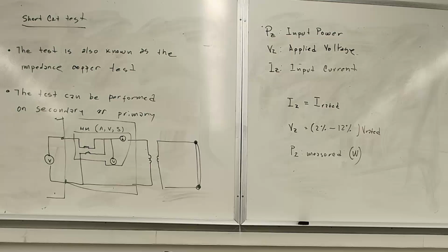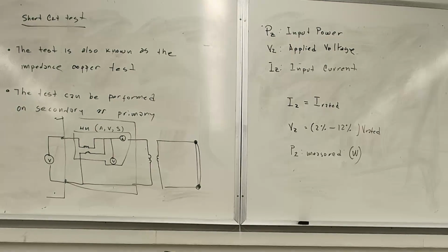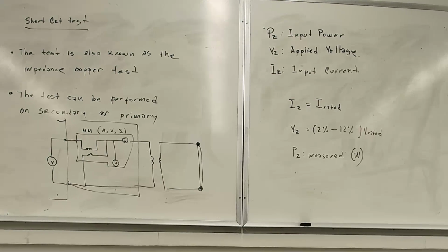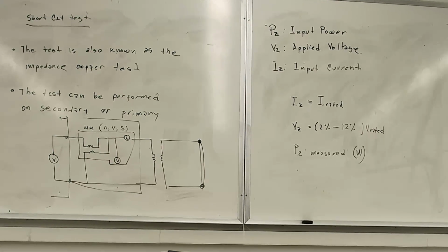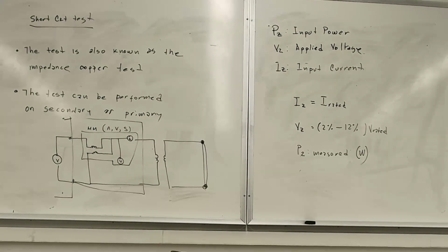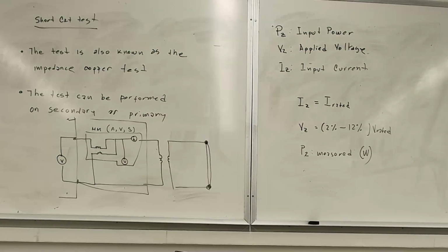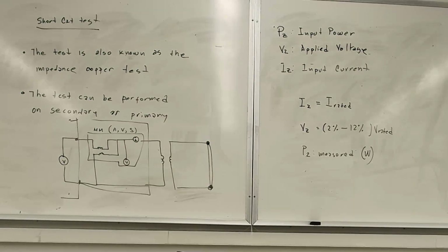So what am I doing on the first test? Short circuit test. And I'm gonna go back to, because we do something similar on the induction machines. We did induction machines, Maria, and synchronous machine already parameters. We did both. Synchronous machines, right? So it's a very similar setup, and all you do on the first one is you take the source, and that's why you gotta have a variable source, and you start increasing the voltage, right?